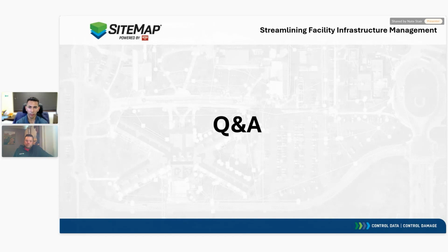But I'm sure Nate could speak to it a bit more, maybe at another location. Yeah, we've certainly completed those projects in the past where we invert all the depths on the utilities we locate, and we model those into the above ground 3D scan. So it's been a pretty effective way to run your clash detection, really get that full picture of what's underground and how it relates to the above ground. So that's a great way to view and access information through a 3D model.